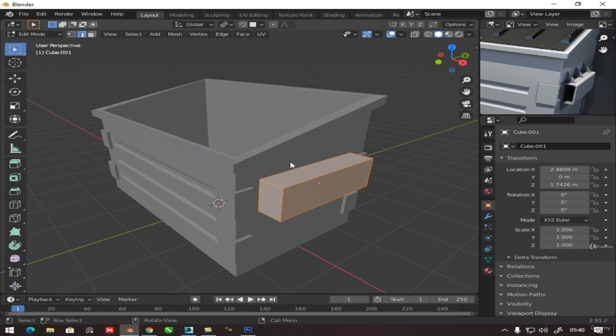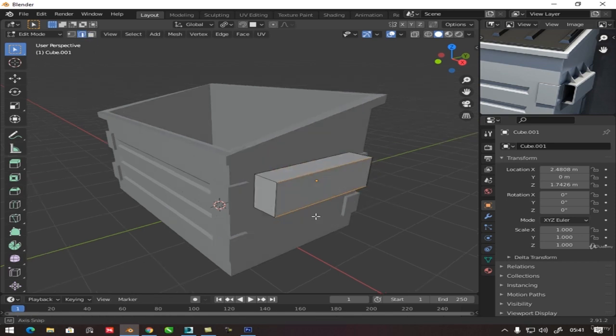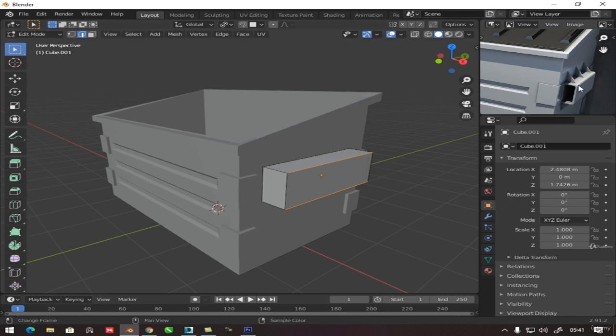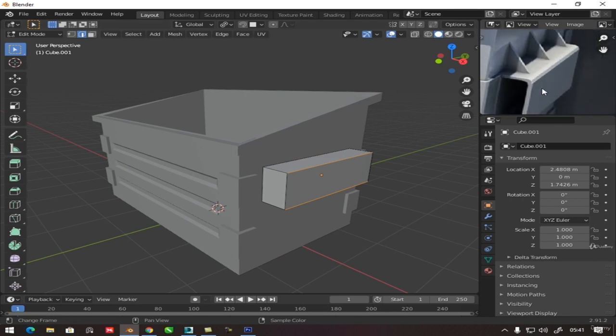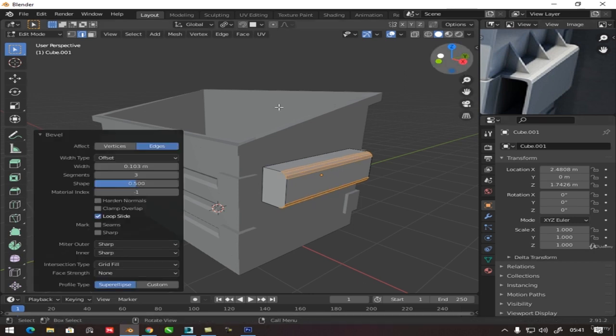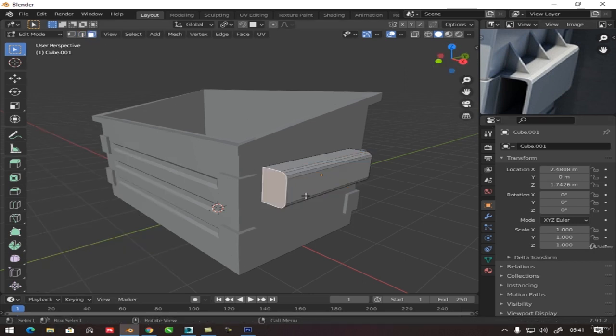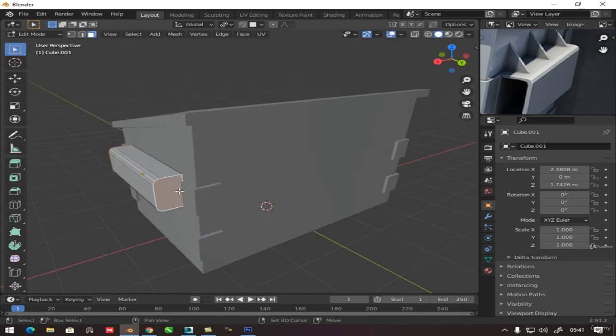Apply scale, get into the edit mode of it, I get to the selection by edge, I get this edge here and this other one below, this and this, and I'll give it a bevel here. There's a slight bevel, it's slightly round, so we'll do the same. So Ctrl B, this way. I roll the scroll of the mouse to give it a little round, basically like this.